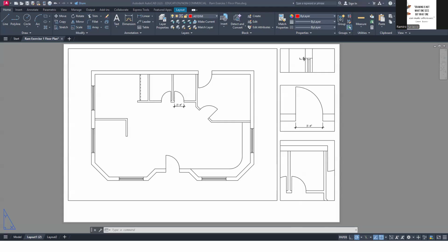Okay? Number one, layout, proper scale. Some of you are adding dimension even if you're not yet in the right scale. What will happen? You add a dimension and the dimension is at a different scale. So you have to add it in the proper scale. Very important. You think it's not, and then you say, okay, what's happening? Well, how come it's showing here, not there? I don't know. What did you do?